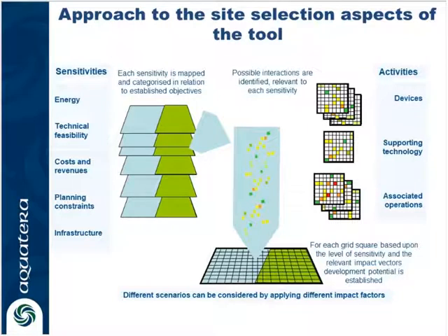This allows the user then to weight each aspect of each data set uniquely. For example, for water depth you can create custom depth bands and create a suitability weighting for each depth band. And each subset of each data set is scored this way for each development type. So devices, cables, moorings, installation and maintenance operations, landfall, overhead lines, buried cables, the list goes on as to how this can be used to find the best sites for the different components of a development.